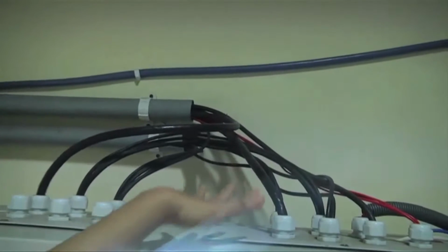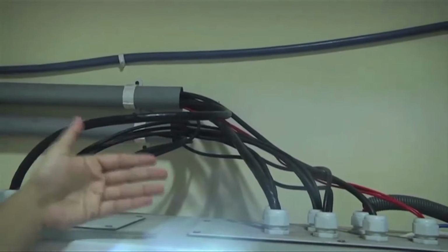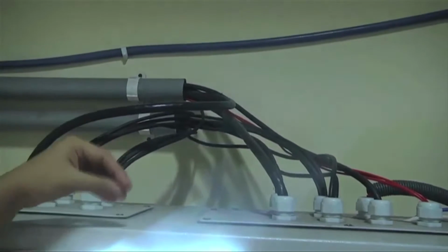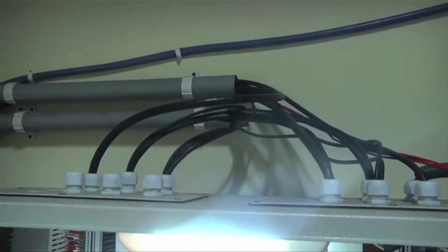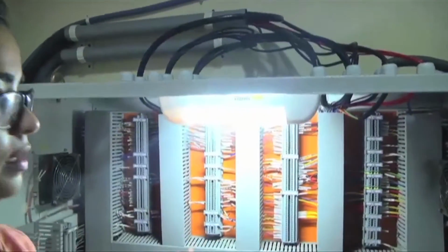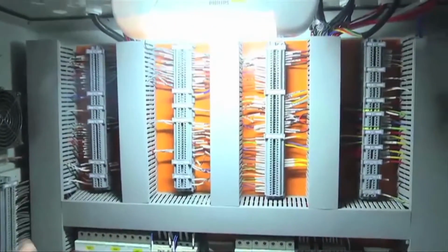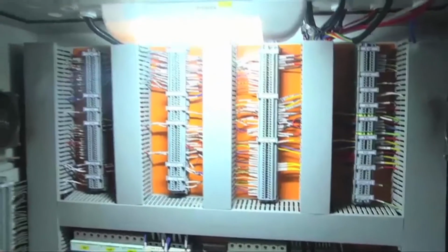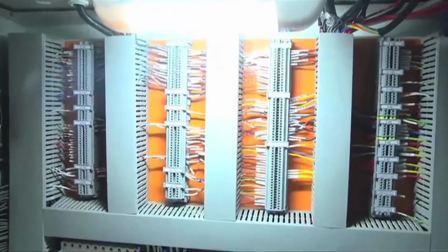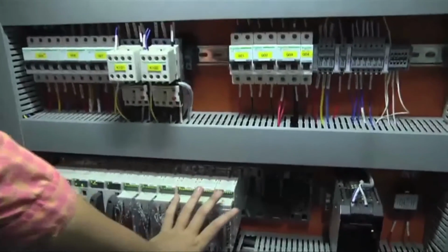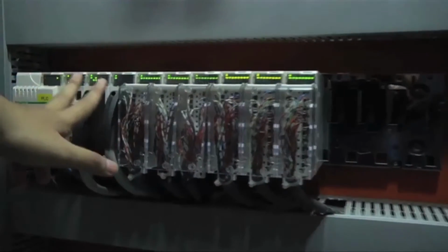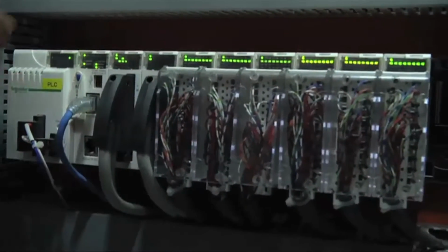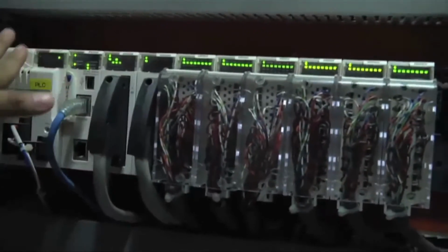Sure, sir. As you can see here, sir, the system of wires here are connected to the sensors on the top floor where we had already seen the system. So all the pressure signals and the flow signals are in analog form, and it is transferred through the system of wires to this location. So all these components here are basically to change the analog signals to digital form. However, this is the main part of this system, where these are the analog input signals, these are the two analog outputs, and these are the digital outputs. And as you have already mentioned, this is the PLC.